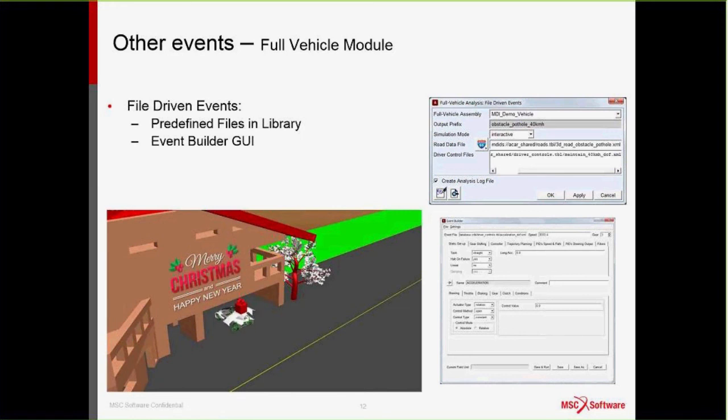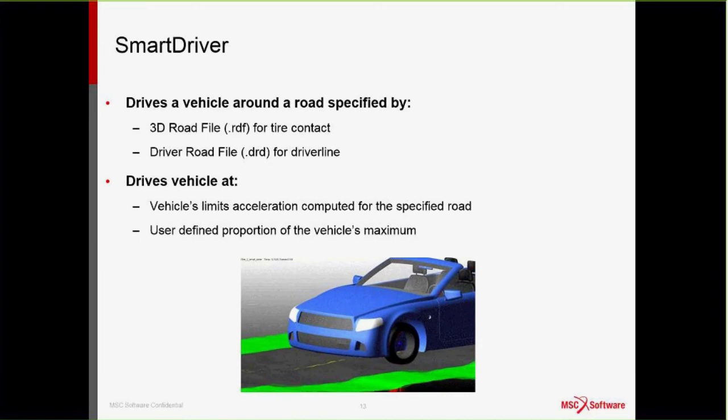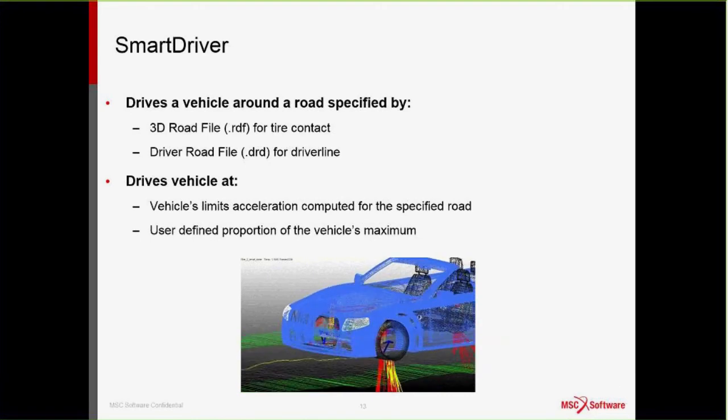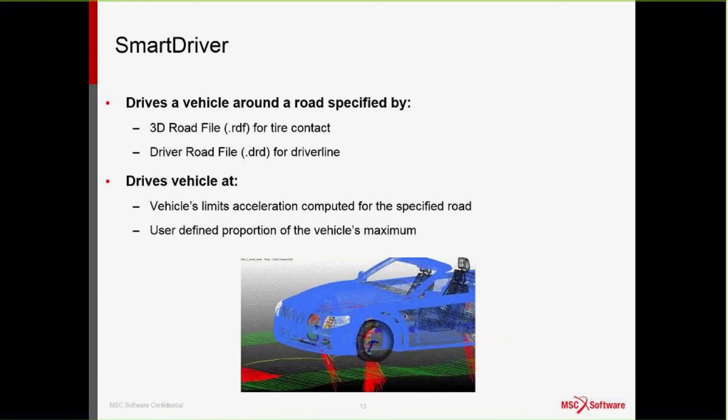But besides the open loop events, you can also define closed loop events using the event builder. By closed loop event, there is a closed loop controller within Adams Car, called the SmartDriver.